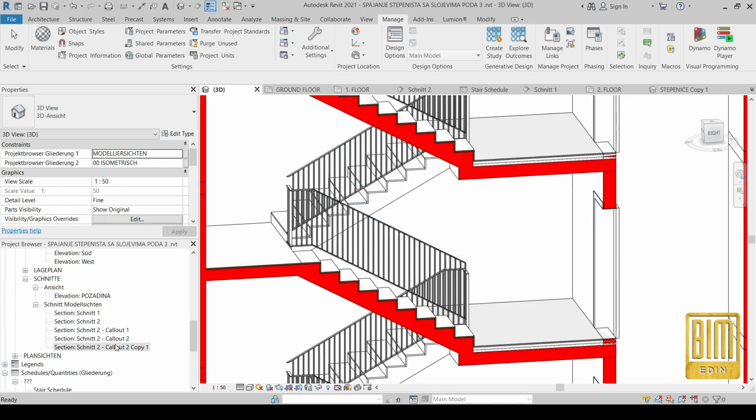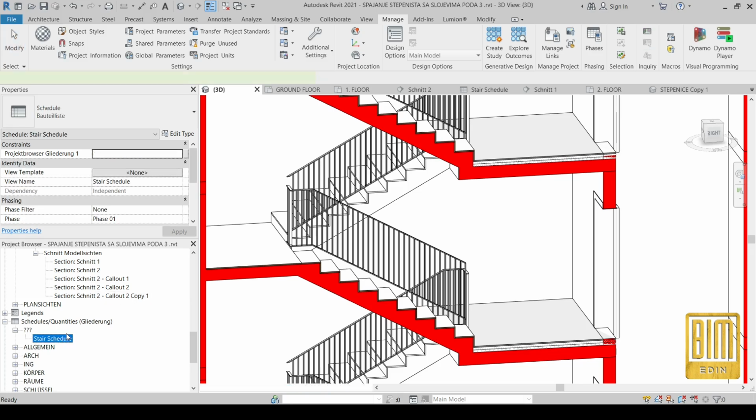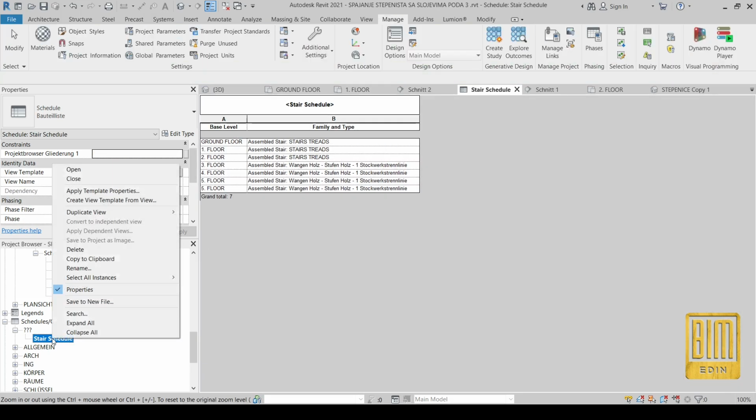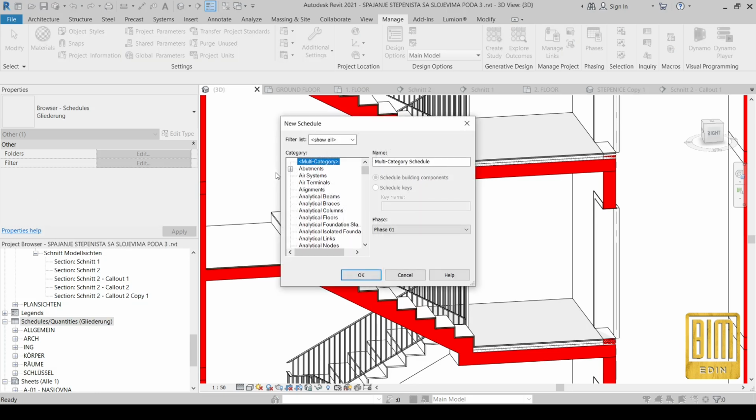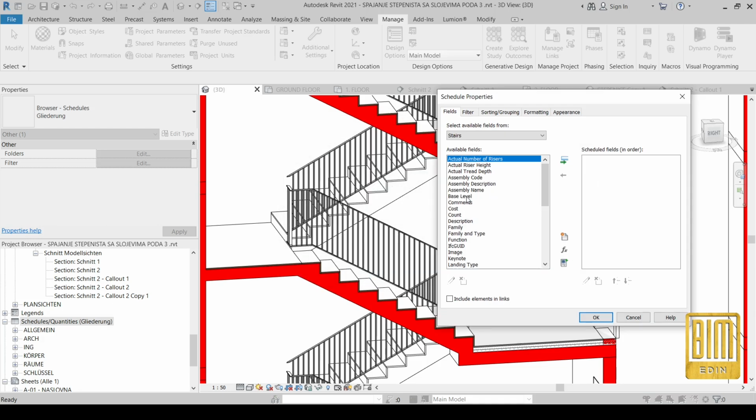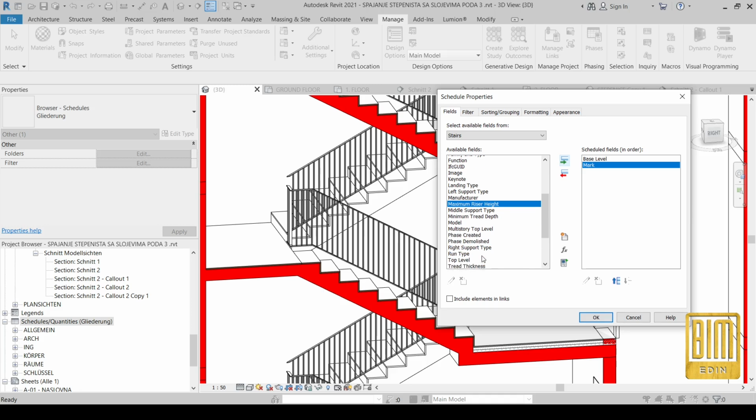One reason more, I remember now, one reason more why I modeled the structural part of the stairs using generic model in place: because when we select it, we can see the volume of that model, and that's the way we will add the volume quantities of these stairs.